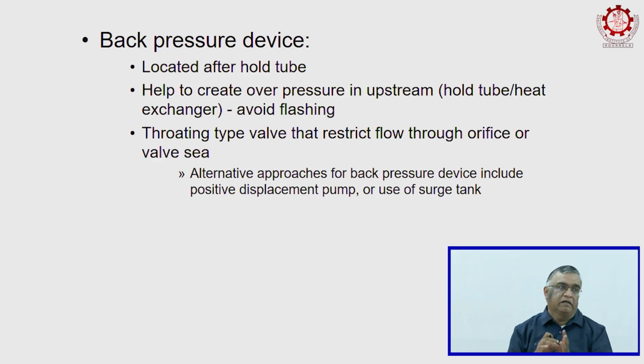So, this is where a back pressure valve comes in. With a back pressure valve, essentially you add some additional pressure to the holding tube, so that it increases the pressure within the tube. When you increase that, your liquid remains a liquid, but at a higher temperature. It may be at 130, 140 Celsius, but it flows as a liquid. If you don't have the back pressure valve, it's going to start flashing or becoming like steam, and that can create a lot of problems.